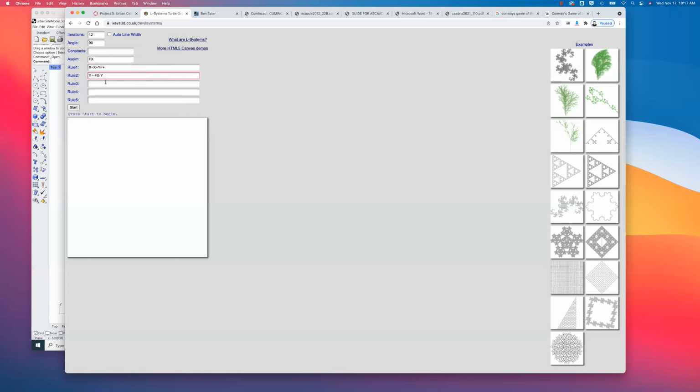But they're recursive. And they basically start to grow through a set of ticks or iterations or generations, as you'd like to call them. If I set my generation to 1 and press start, I get nothing. I'll take generations to 2 and start. I get something very simple, a line, and the branch then turns into a line and a line. So things are turning at right angles based off of these rules. Try 3 generations. Okay, 4, 5. And this is all just drawing a line and rotating by 90 degrees according to these rules.